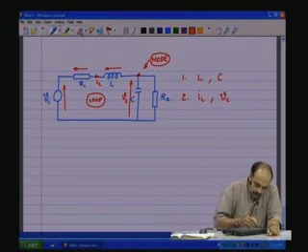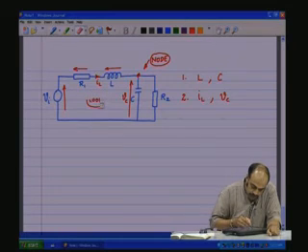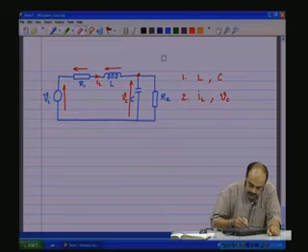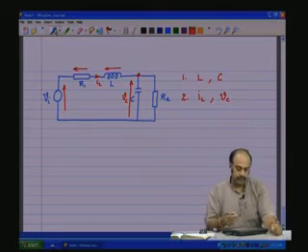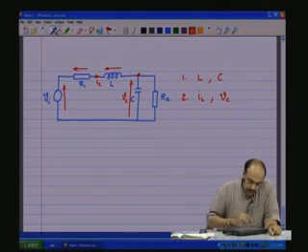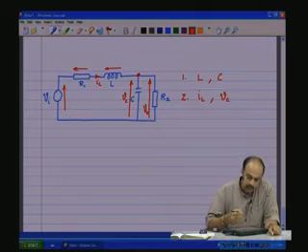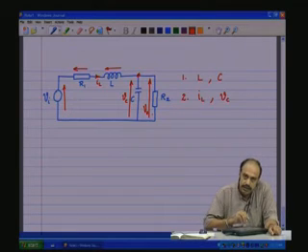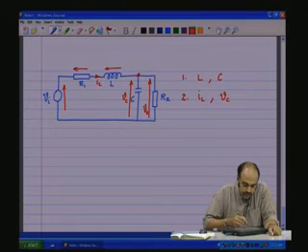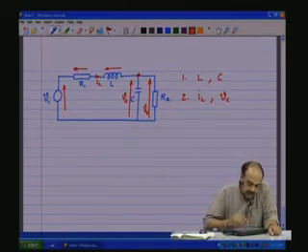Okay. Now, let me erase these things so that it will not disturb the overall picture. Yeah. So, now it is required to have a look at the output voltage V naught. Note that V naught can be expressed in terms of the state variables. This is the output, the Y that we use to describe, which is in this case the same as Vc.